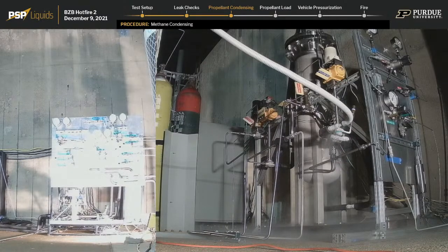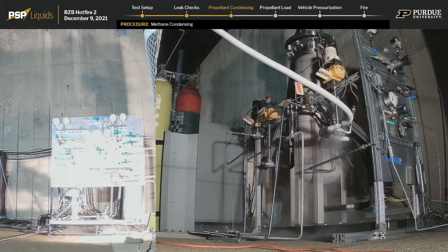Yeah, so our vent lines will often have liquid coming out of them, especially at the end of an operation. It's very normal to see liquid coming out of these to just verify that things are actually moving through the system. Right, and the good thing about having liquid coming out is because our vents are in the top of the system, we know that means that liquid is making it all the way through the system, which means we know exactly what temperature we're at, and we can begin methane condensing without having to worry about freezing or losing methane to the system.